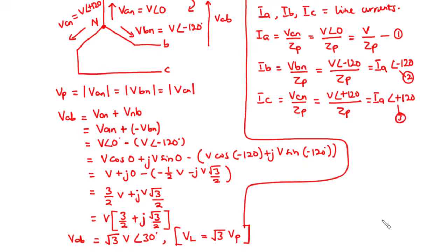Now what this primarily means is that the line current IL is equal to the phase current IP in a star configuration, and both the line current and the phase current have the same phase. Notice also that adding up the 3 line currents, that is IA plus IB plus IC, is equal to 0, so that the current in the neutral is equal to negative of the sum of these values.